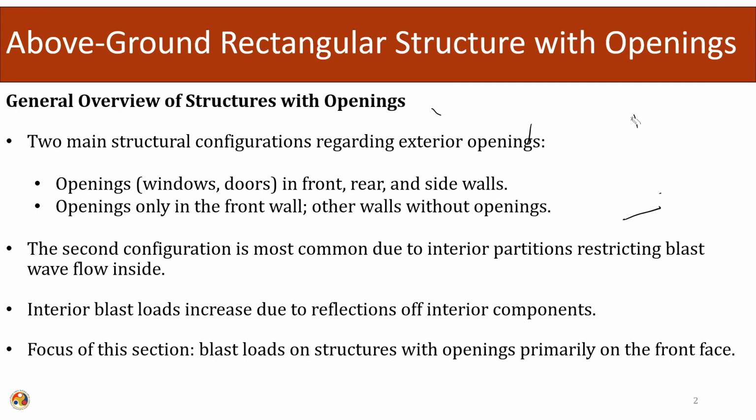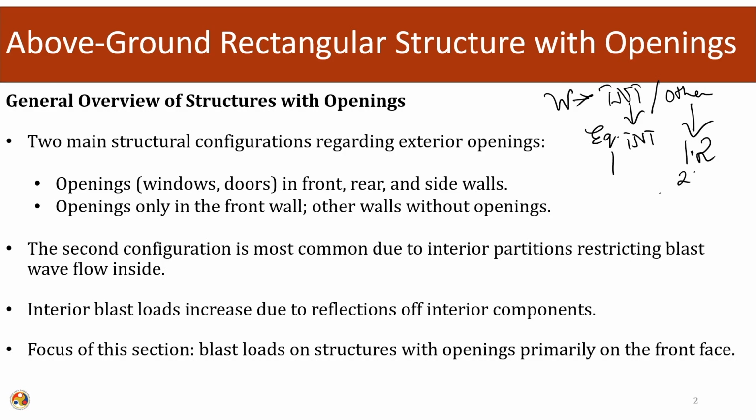First we need to see what type of explosives we are having. Depending upon whether the weight of the charge is made of TNT or some other explosives, we convert it into equivalent TNT. If it is TNT, then we just multiply it by 1. If it is made of some other materials, then due to the uncertainty, we multiply it by 1.2, that is an increase of 20%. So, this is the characterization of the explosives.